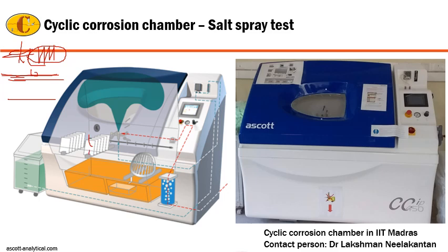So you can put in panels of your steel that is used in the industry, the pipeline, and you can program it to get the cyclic nature. The corrosion that occurs on these will give you a more accurate picture of how the corrosion will occur. Then you can take these coupons and do the previous tests to see how their properties have degraded.